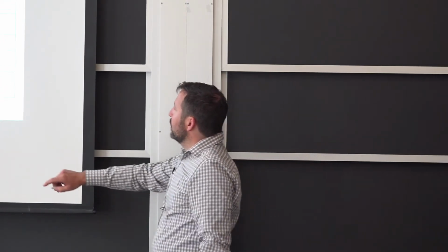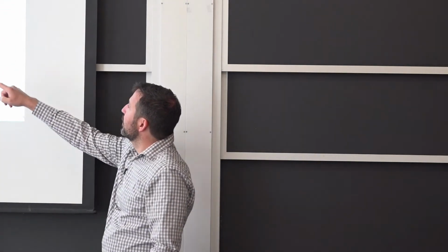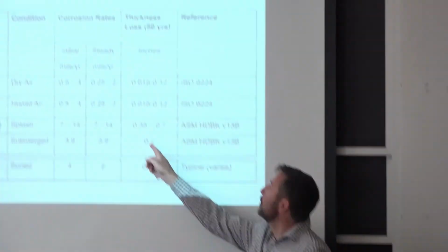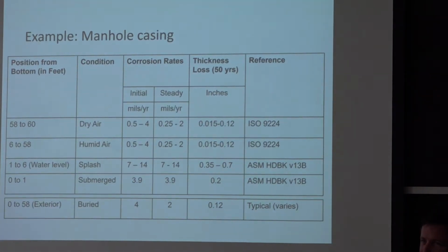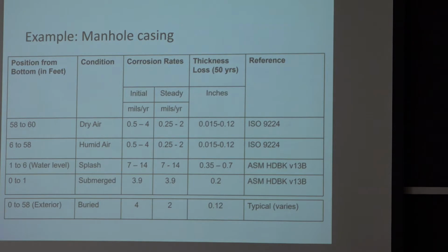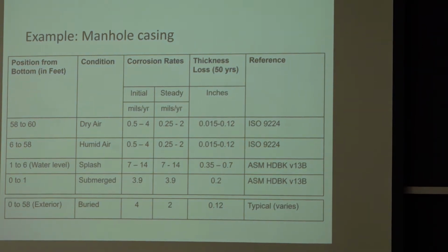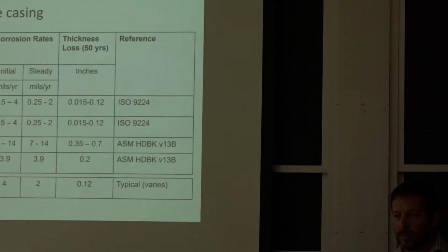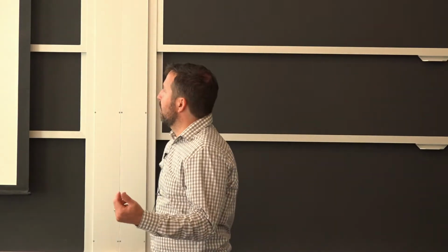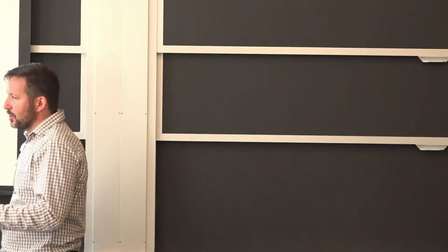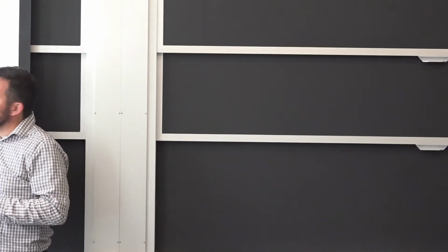So from that number here, if you want to lose 0.2, it's 50 years. Actually, it's a substantial time. But the piece of information there is you're assuming homogeneous thickness loss, which really almost never happens. So the case of getting perforation with something that's very thick, a 1/4 inch thick, would be half that 50-year life, so about 25 years.